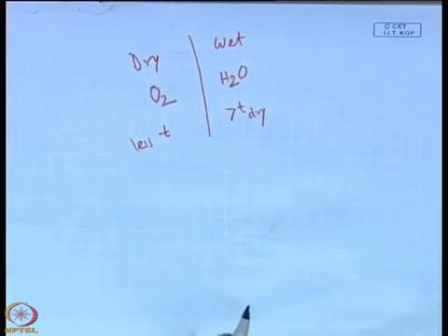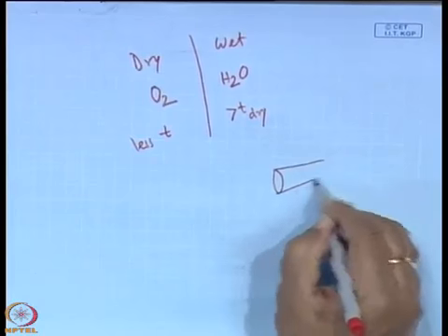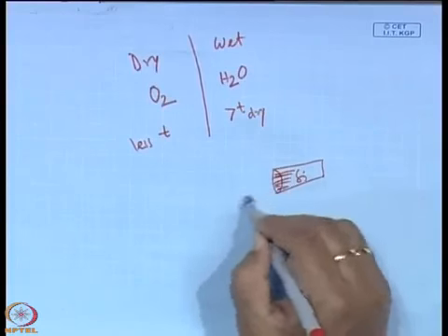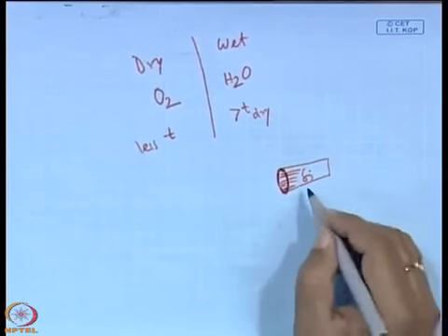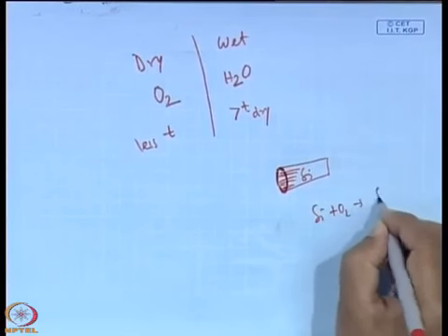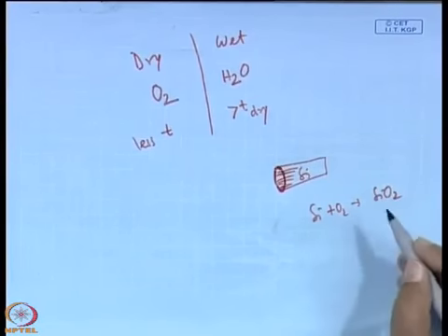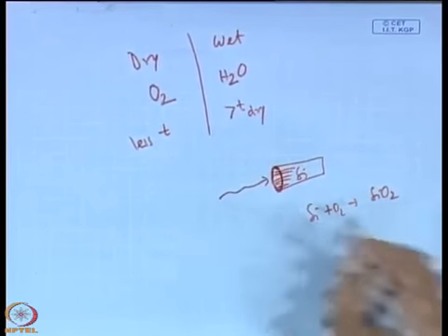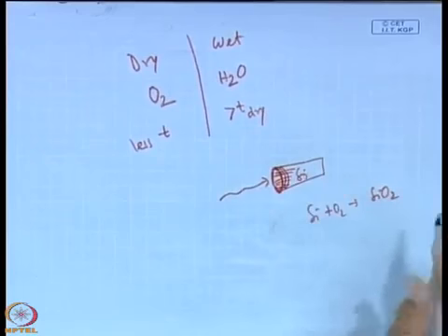We have also seen the kinetics of growth: first a layer of SiO2 is formed on the silicon. The first rate limiting factor is the reaction of the Si with oxygen to form the SiO2, which is linear in nature, and the rate constant depends on it linearly. Then the oxidizing species diffuses through the SiO2 layer to reach the surface for the reaction, so it can be the parabolic rate constant.